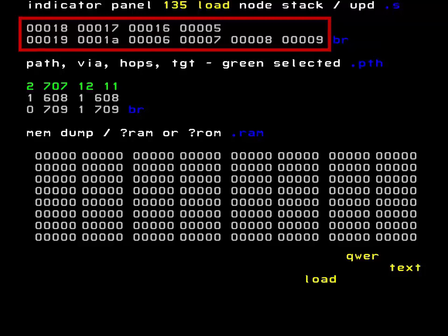When I press keys with non-printable characters, for instance space, enter and escape, you can see call instructions instead of character codes. Function keys are encoded as messages with bit 17 set, with the low bits corresponding to the number of the function key F1, F2, F3. It demonstrates that the host takes care of this newly attached keyboard and node 11 does not need to be aware of what has happened. It just shows characters as they are received.